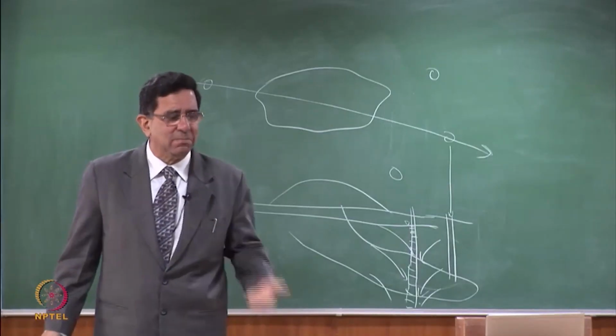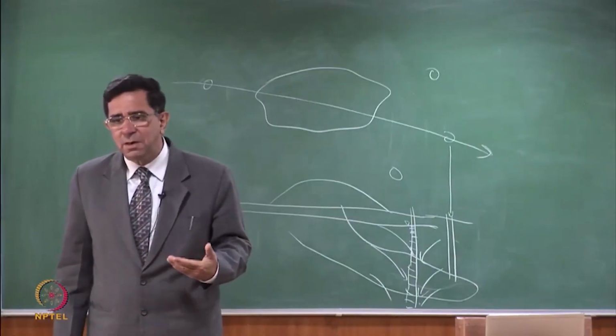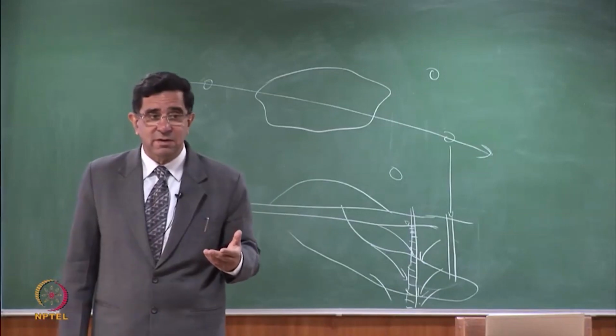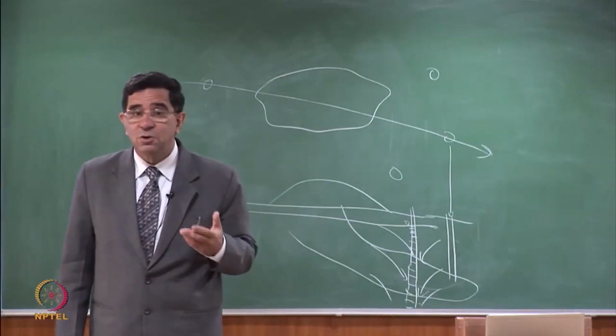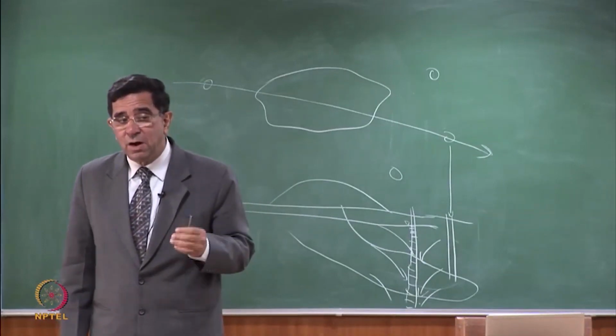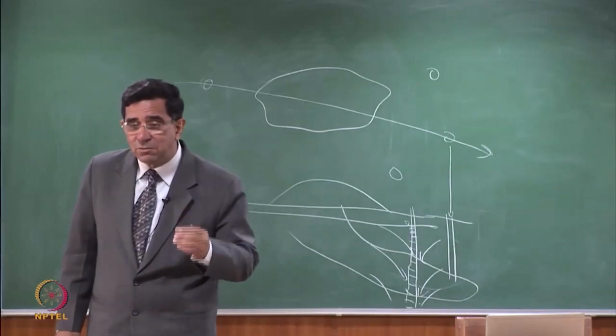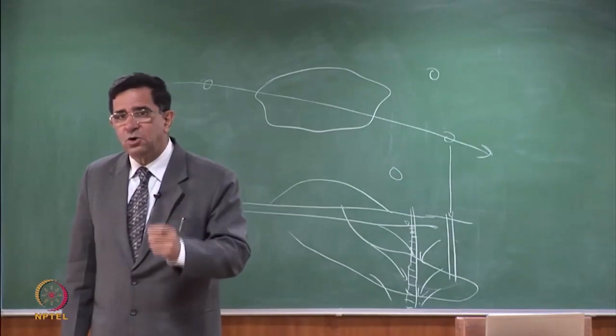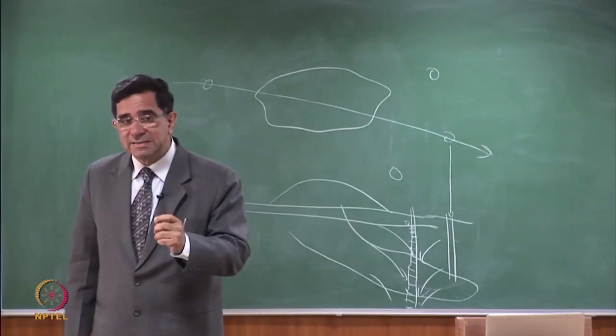No, that is all right for drinking water. What difference does it make to you? Water should be drinkable, and you have a thick 25-meter aquifer. It's not all right for environmental studies. So well cluster means you are trying to pick up 3 samples from 3 different depths which are isolated from each other. Water should not mix.